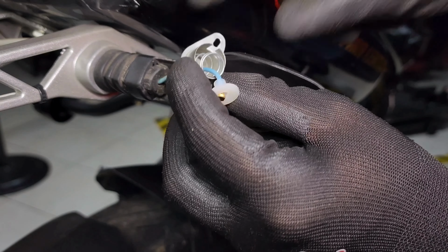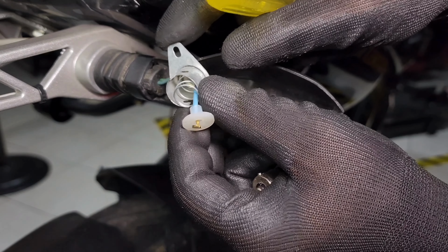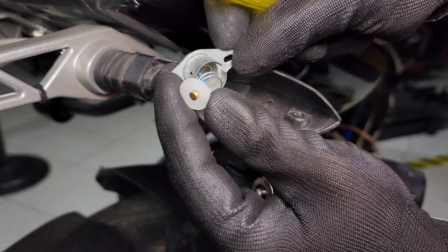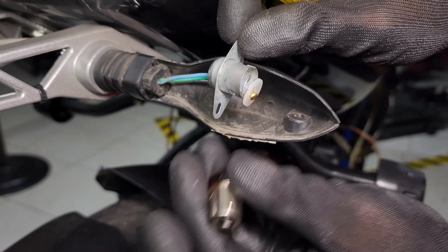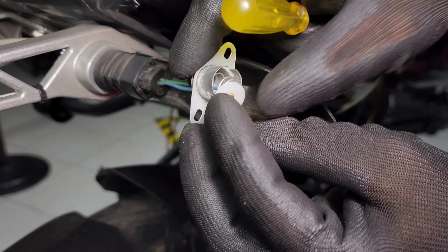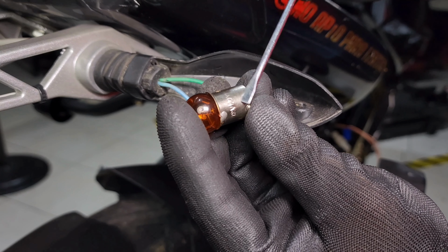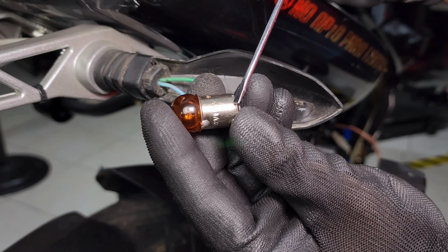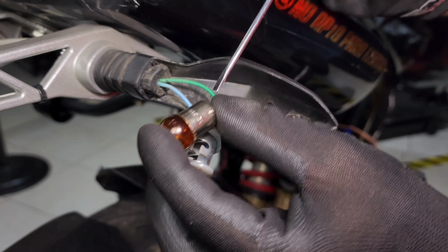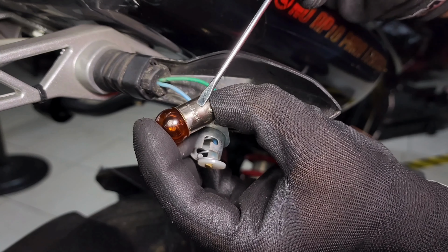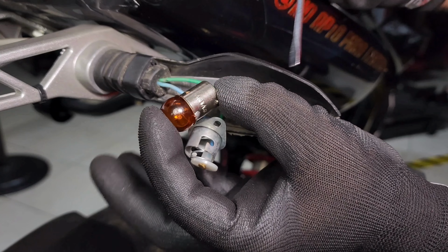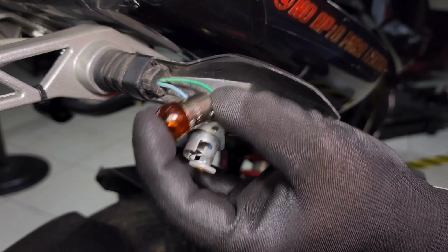As we can see, this socket is leaking on the inside and this can generate a false contact with the light bulb, and that is why it sometimes generates the flashing. Because this light bulb is also 10 watts. It is not original, bad luck. It is 10 watts and in practice it is a 12 volt 10 watt electrical component. It should generate the same consumption of amps.